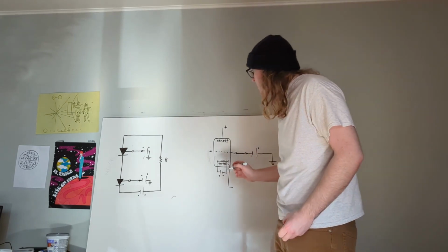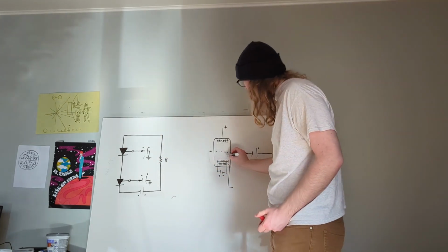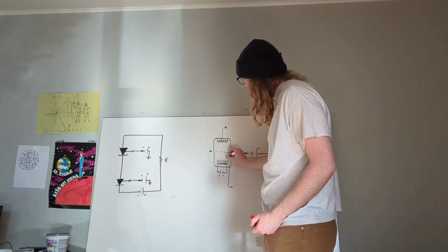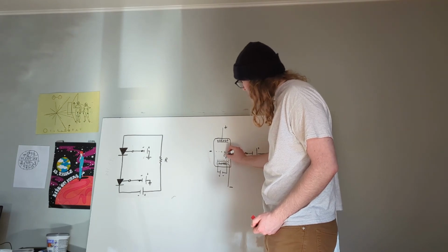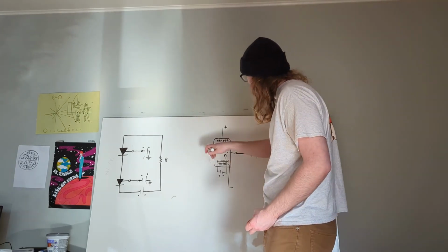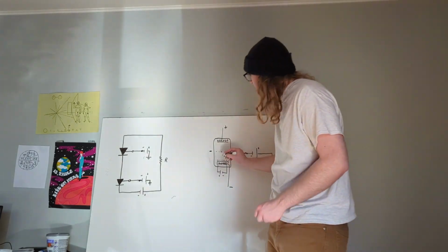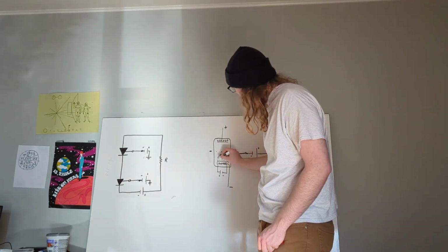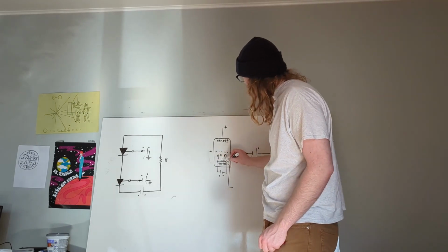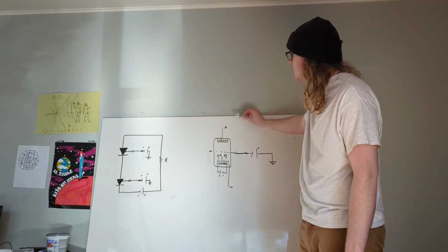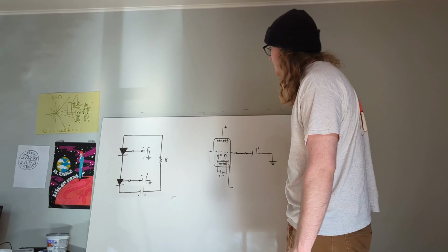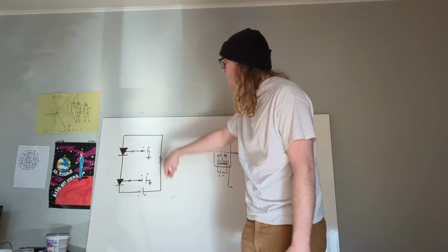So when the original circuit is run, we can expect that from this negative cathode source, electrons will be emitted via thermionic emission. But because a negative voltage source exists across this grid, and with the idea that like charges repel one another, the negative electrons will be redirected, and no current will be allowed to flow through the larger circuit components. So it's essentially acting as a voltage switch in our larger circuit.